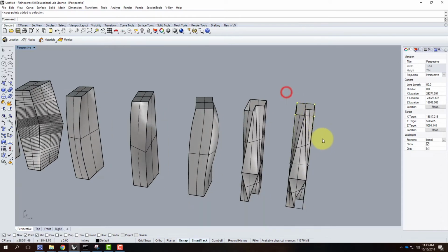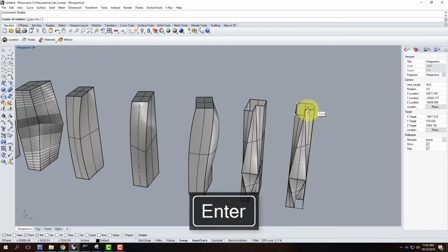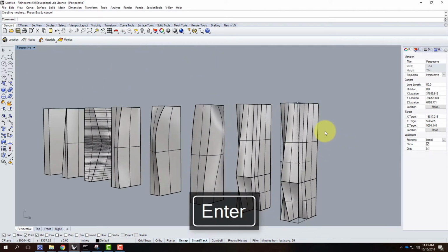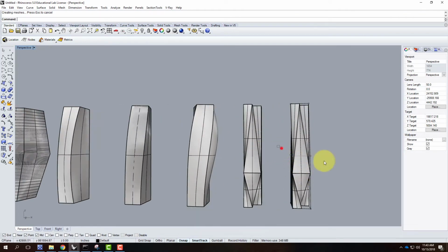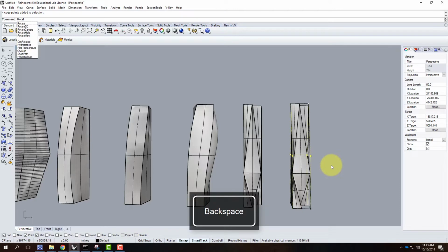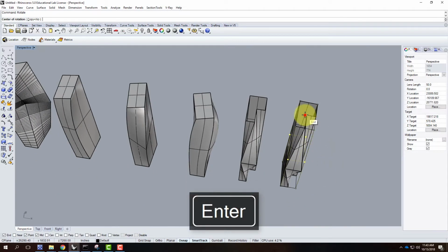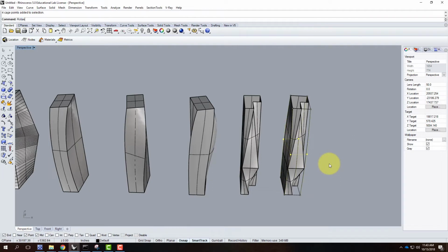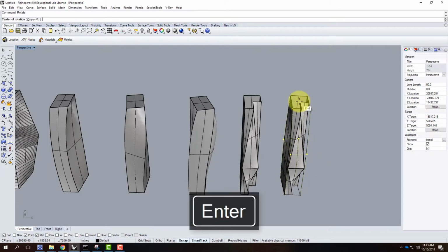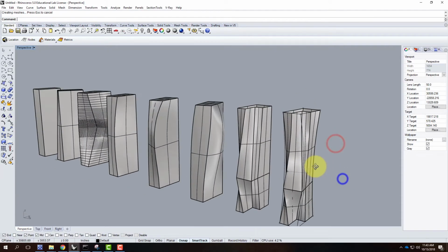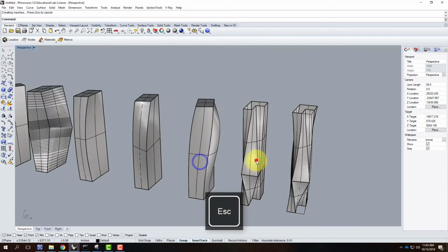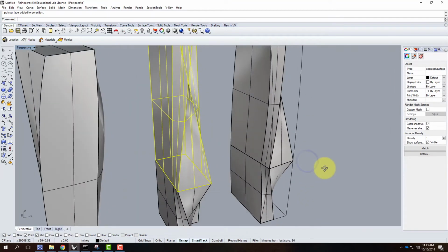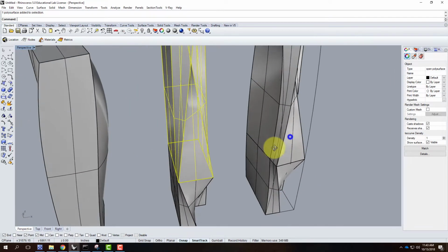And I could say, you know what, I want this one to rotate a little bit. Maybe by 5 degrees. So it's just off. And I'll take this first piece, take that one right there. We'll rotate that one 5 degrees. It goes that way. Maybe I need to exaggerate it so you guys can see it a little bit better. There we go. And so the point is that I'm transforming this shape into something that's even more twisty. And I can get away with that because Rhino will allow me to do it.